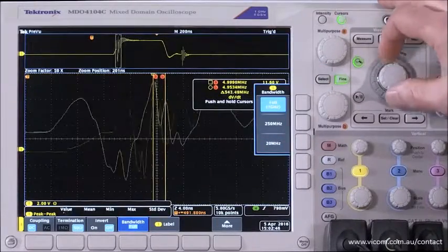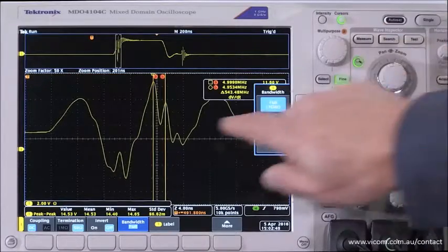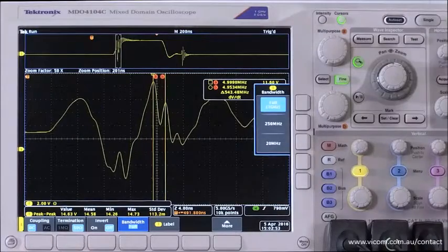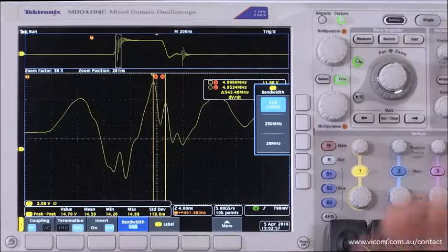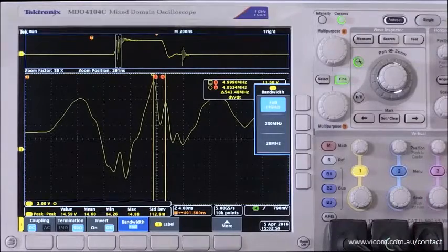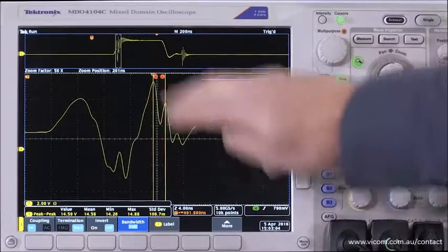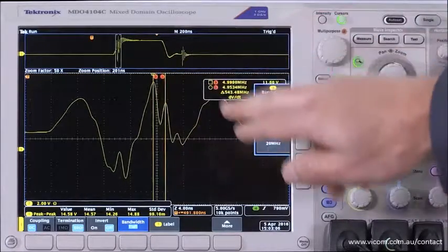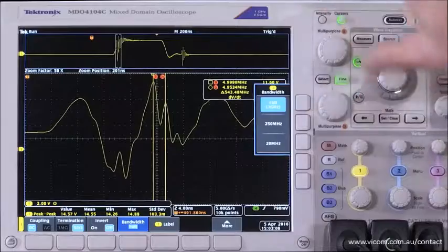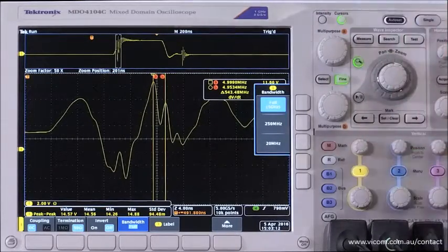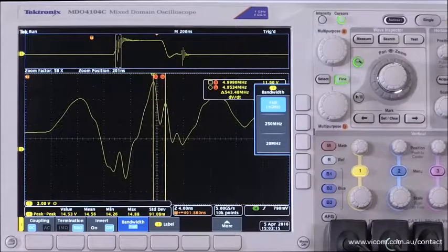So right here, the cursor between those rings is about 543 megahertz. So with that 20 megahertz measurement system before, invisible. 250, I see a hint of something, but I don't know what it is. A 1 gigahertz system, I can actually get in there, see that it's a 500 megahertz ring on top of my 100 megahertz resonance, and allowing me to go through and figure out in my circuit, the devices, what's causing